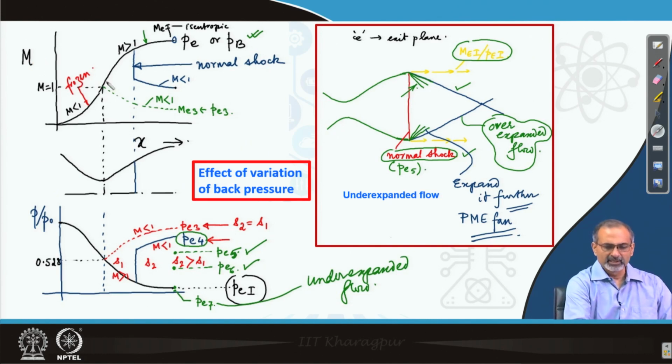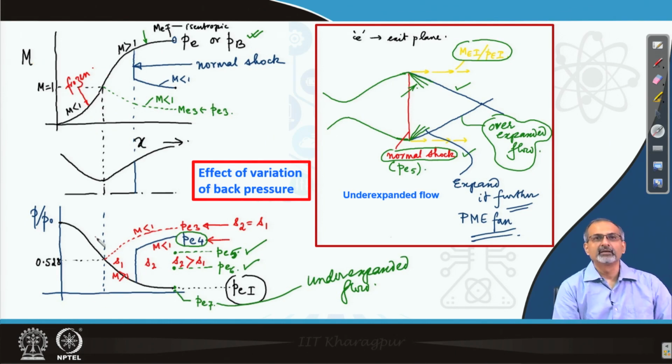As you can figure out, this is the throat where the flow becomes sonic if it is choked, and the pressure ratio becomes exactly 0.528. Then, based on what kind of back pressures are maintained outside the exit of the CD nozzle, different kinds of conditions may be created which are either isentropic or non-isentropic in the diverging part of the CD nozzle.